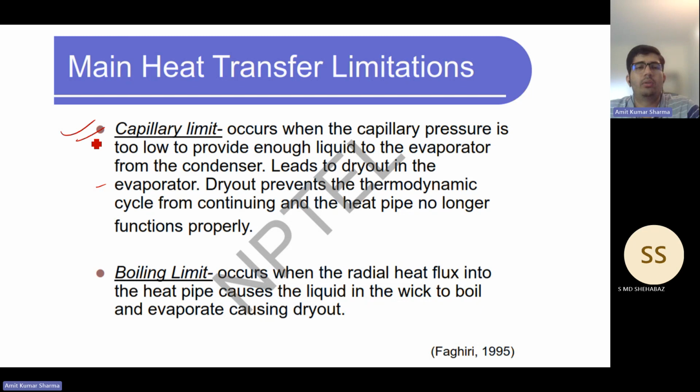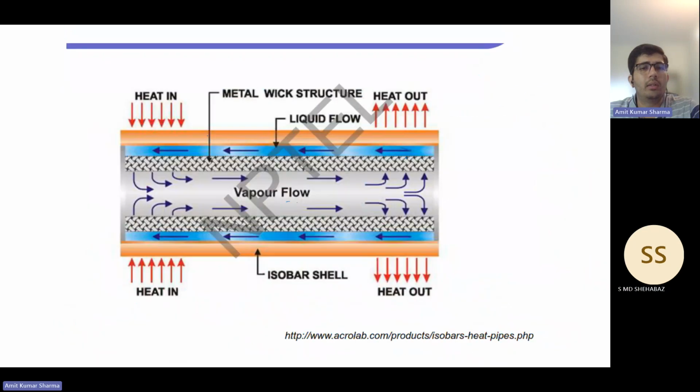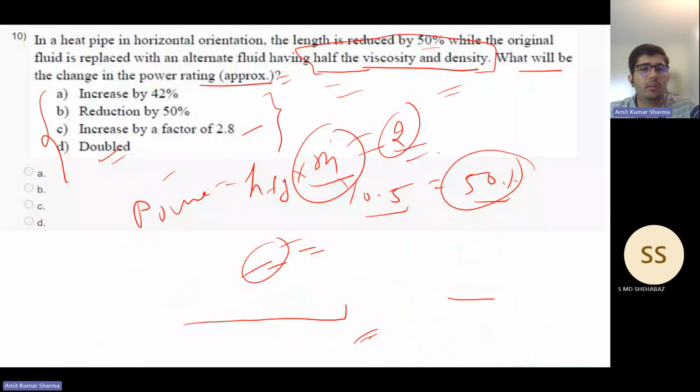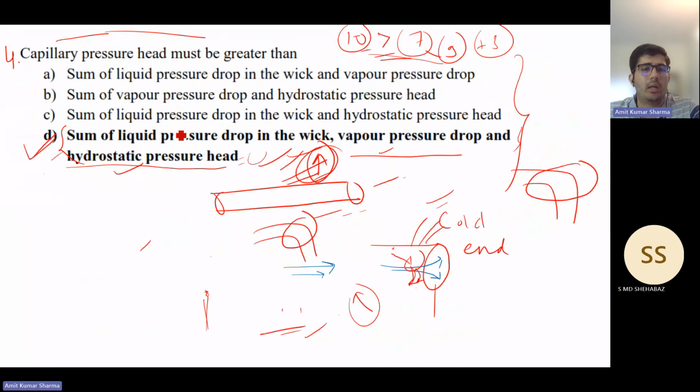It's very important. So the capillary limit should be there. The capillary pressure drop should be more than the pressure drop of the liquid, the hydrostatic head, and the vapor pressure head. Another one was what? That question, I think, was liquid pressure drop, vapor pressure drop, and the hydrostatic pressure head.